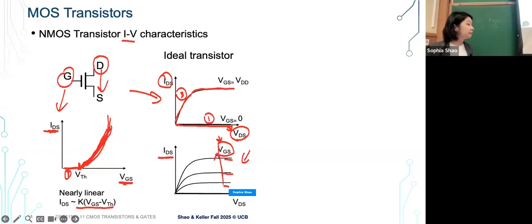The time it takes is the... Oh, you mean how fast the circuit charges and discharges? Yeah. Let's say you have a fixed amount of electrons stored in your capacitor. If you have higher current, it charges and discharges faster, right?